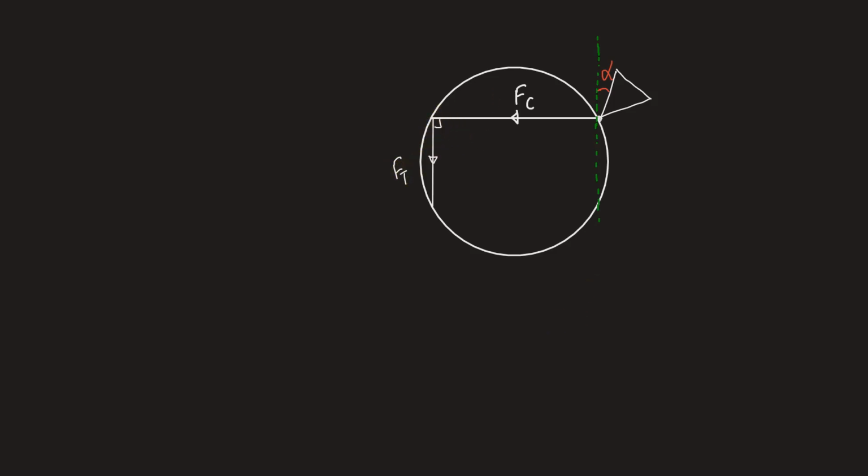We have the friction force in this direction. So this friction force is such that this will also make an angle equal to alpha with the vertical axis but on the opposite side. Now we can plot the normal reaction like this, perpendicular to the friction force as always. So this angle is 90 degree, this is 90 degree, this is friction force F and this is the normal reaction N. Therefore, the resultant can be shown like this.